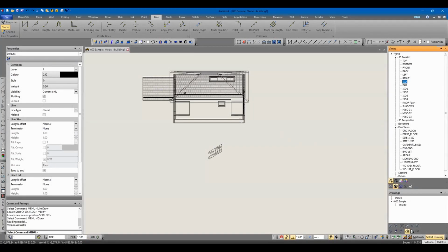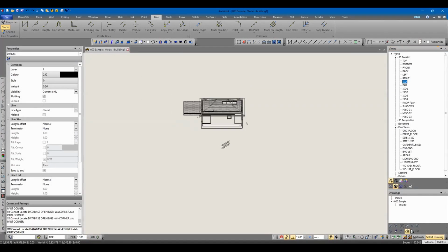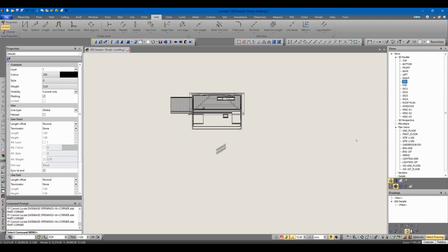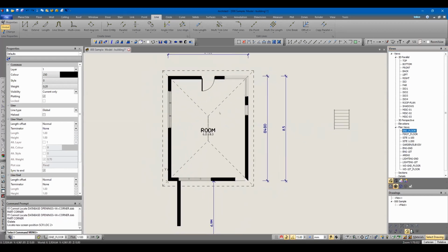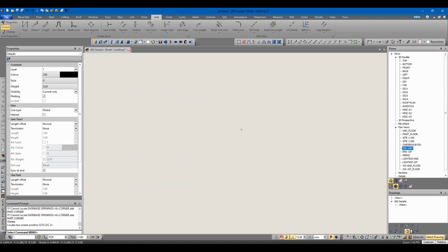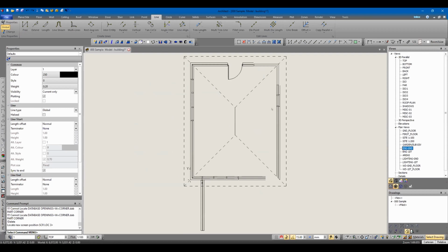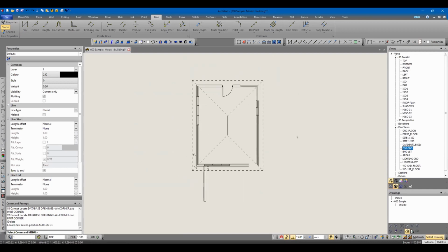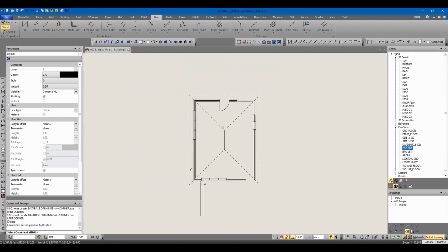Somebody was asking what we do to get drawings out for an engineer. Normally we've got our sketch design setup. If I wanted to get this out as a DWG, we have several different views, so I set up a view specifically for the engineer. In my engineer view, I turn off the hatches in the walls and most other stuff, so it's a nice, simple, clean template for him to use.